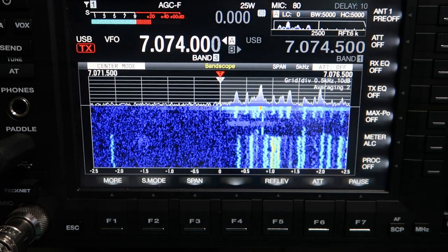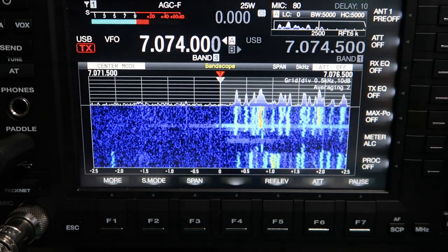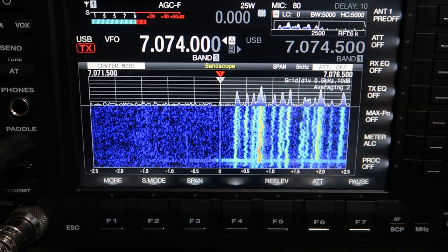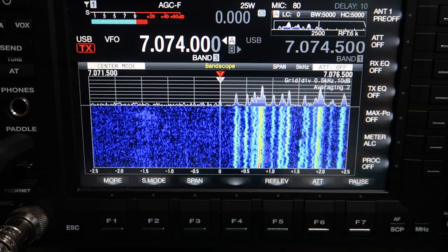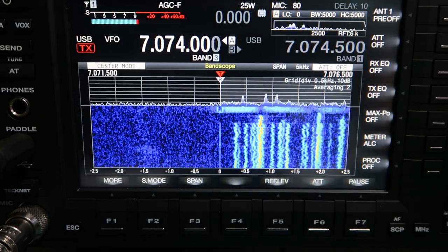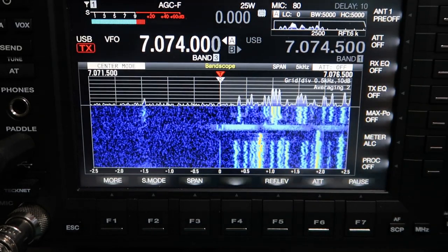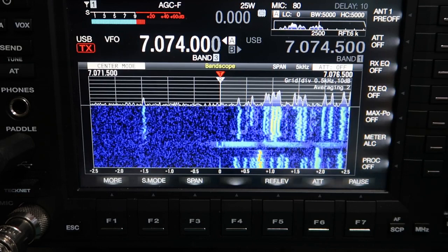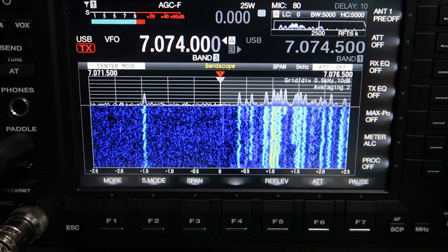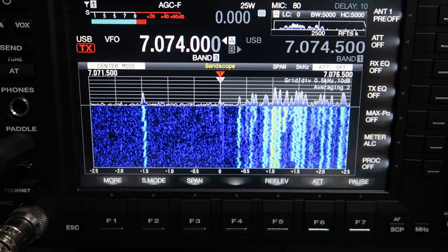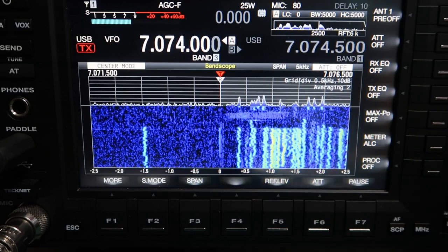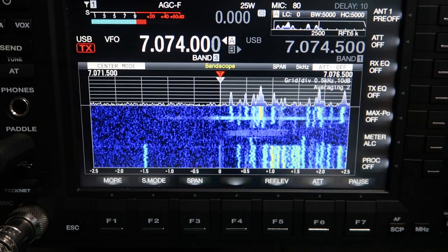So the first thing to understand about the TS-890 is that it's got a lot of options available for how you source audio for your transmissions. Traditionally, you'd put your audio through a mic socket, and in normal SSB activities, that's the way you'd work it. But when we're running an AFSK mode, like FT8 or PSK, your audio is coming from the PC, so the rig needs to know where to source the audio from. There are quite a few options on this radio for that, and we'll try and show that to you now.